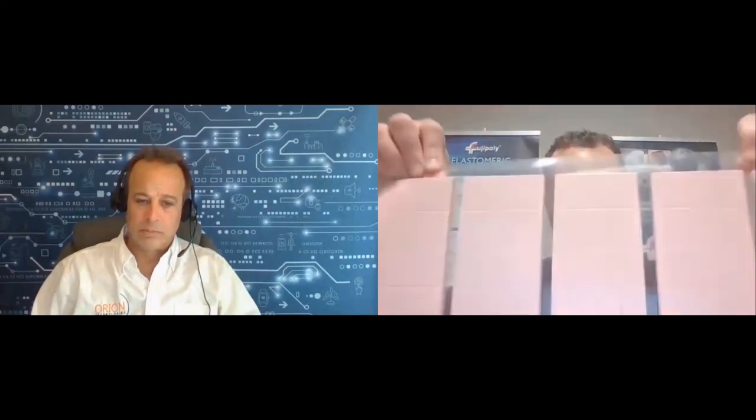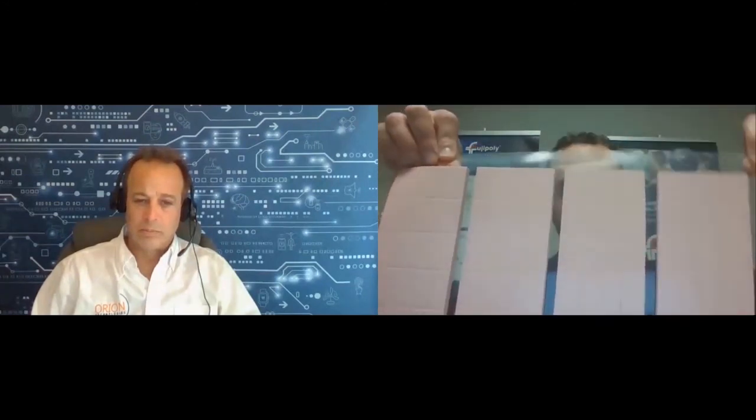Okay. And then the last thing I have here, I just wanted to quickly show an example of what a kiss cut sheet looks like. Kiss cutting is basically where you're cutting through the material, but you're not cutting through the bottom carrier. The advantage is that it allows you to easily remove the top cover film, and what you're left with is basically a laminated sheet with all of these cut parts on it.